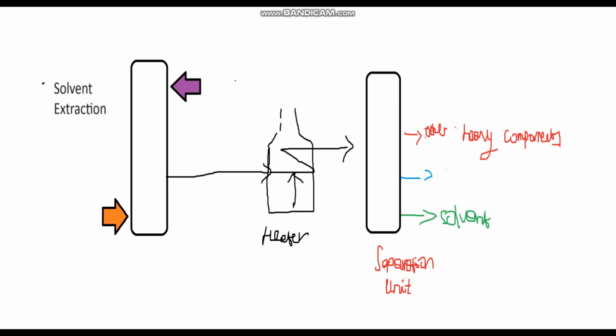So let's go. Feedstock preparation. Yeah, also the same process. First of all, the feedstock is dried and contacted with the solvent in a counter-current or rotating extraction unit. The solvent is separated from the product stream by heating, evaporation, or fractionation. The remaining trace solvents are removed from the raffinate by steam stripping or flashing. Electrostatic precipitators may be used to enhance separation of inorganic compounds. Solvent is then regenerated and recycled.